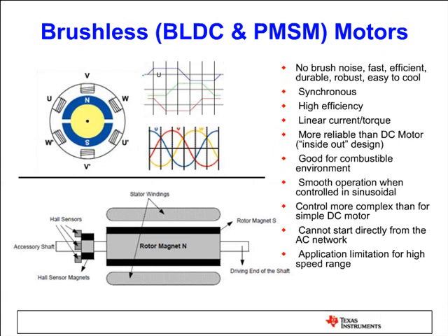So the operation is quite smooth, but the problem is, compared to the brushed motors, the control of PM motors is a little bit more complicated, especially the sinusoidal one. The algorithms running to control the PMSM motors are mathematically intensive, so we need powerful microcontrollers. On the other hand, controlling BLDC is relatively easier, and most cheap controllers can control BLDC type motors.